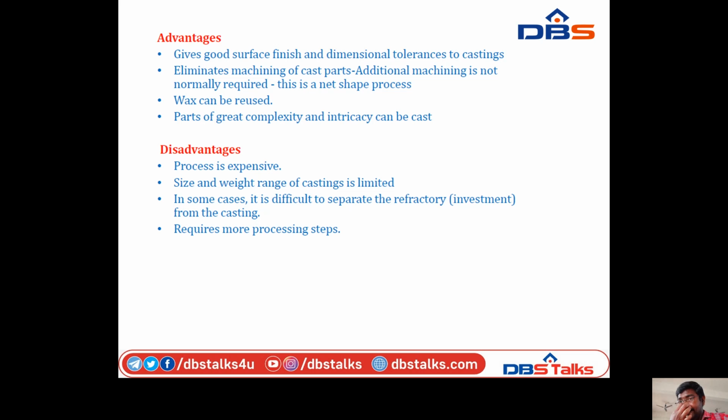Next, advantages. It gives good surface finish and dimensional tolerance to the casting. Eliminates machining of cast parts. Additional machining is not normally required. Wax can be reused. Parts of great complexity and intricacy can be cast.